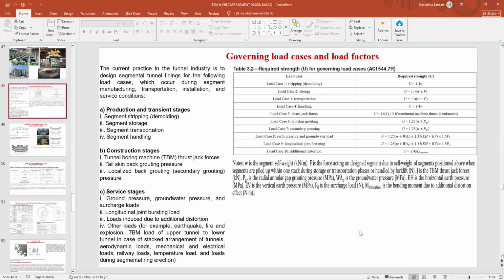Plastic sheet here does not mean the plastic that you are thinking of. It's a separate type of sheet, made taking durability into account, so that it prevents the exposure of the chemicals to the steel of the bolt. Nowadays, in several Middle East projects, they are using permanent bolts. The bolt has a design life of around 50 to 60 years. The manufacturer himself is dictating that his bolt has a design life of 50 to 60 years, and accordingly he is making the arrangement. Okay, sir. So everything depends on your durability.